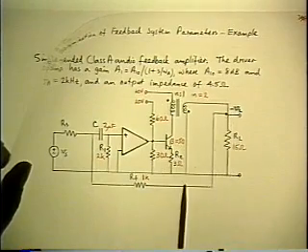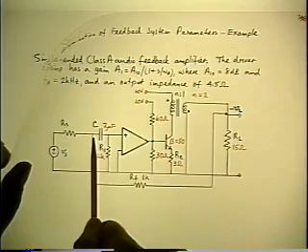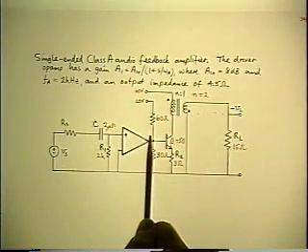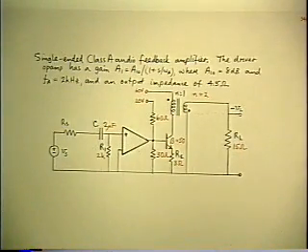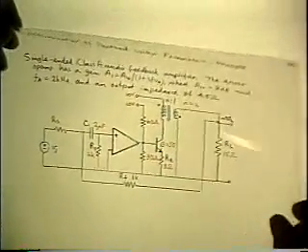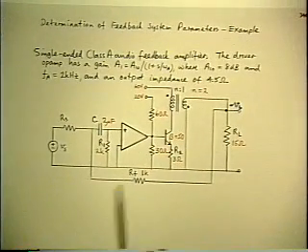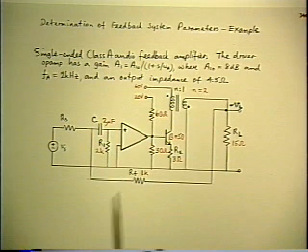Because it doesn't go to ground, really. So that's going to affect the current division in the forward path, and therefore its gain, and you don't know what to do about that either. So again, backing off the conventional approach, let's change the approach to where we have other places to look now for breaking the loop or injecting a signal into the loop.